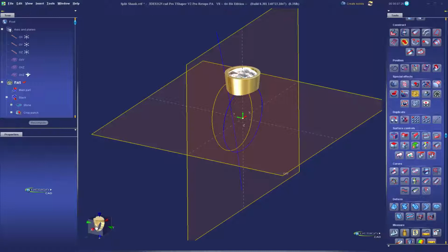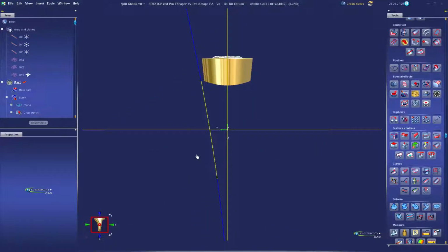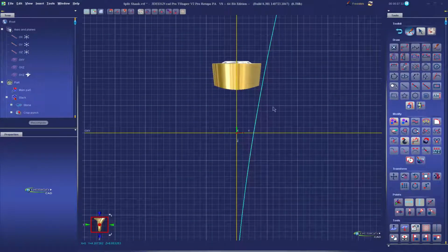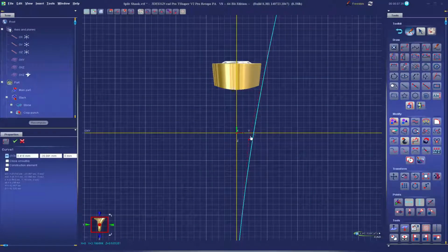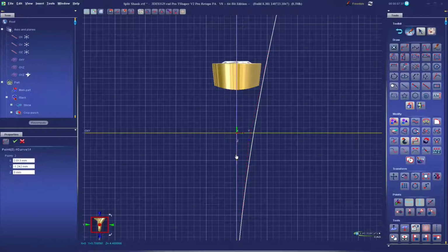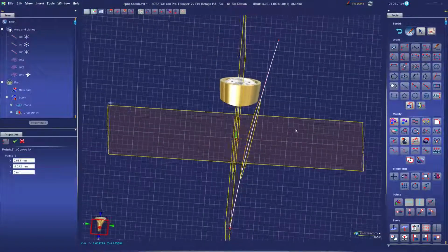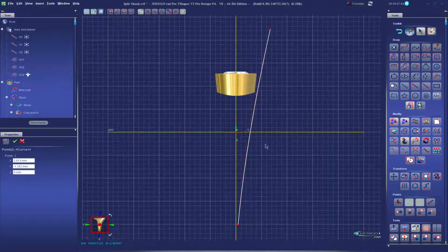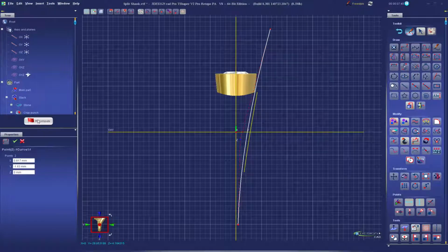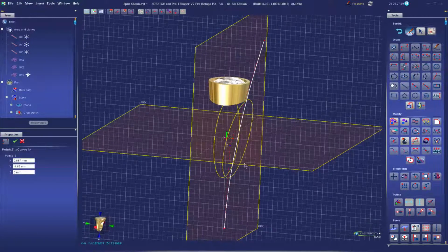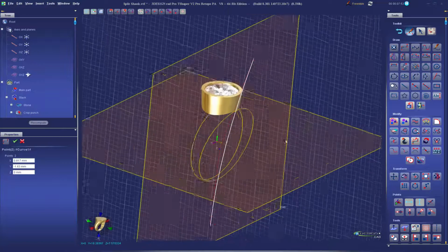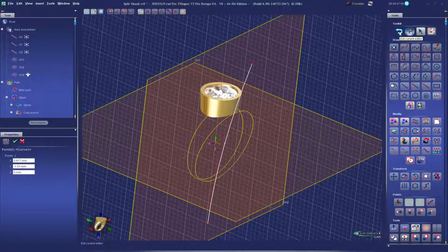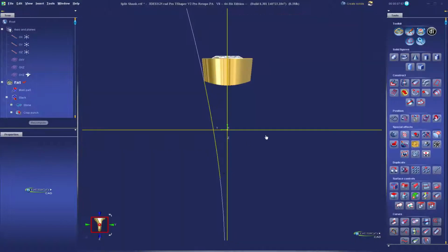The nice thing is it makes it really easy to modify this shape as well. I can just go back into this side view, and I see that I need to bring, actually, I think I have it drawn pretty much the way I want it. We'll leave it there for now. But if you want to adjust the curvature, you can. If you want it to bow in a little more, just move that point in, and notice that the 3D curve moves with it. So very powerful. Let's go ahead and exit the sketch.